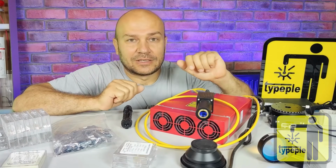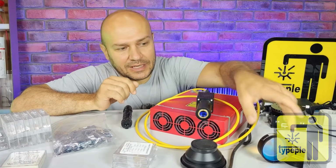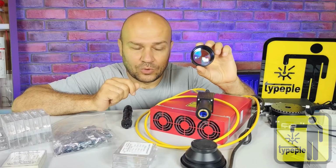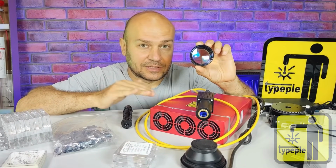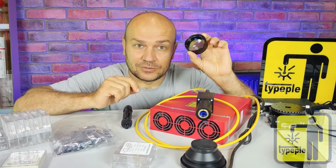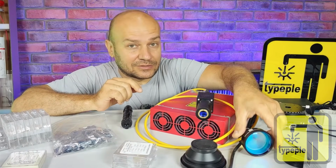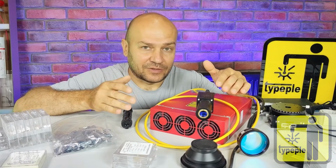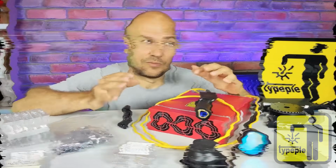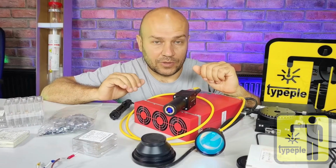The wavelength doesn't interact with organic matter or certain materials like glass or quartz. Again, lenses made of quartz material are used, or ordinary glass if the power of such lasers doesn't exceed 50 to 60 watts. In all other cases, it's better to use quartz, of course. Using these lenses for other lasers isn't recommended because every laser has its own wavelength, so the interaction is completely different. As for the lifespan of these lasers, the figures vary everywhere.